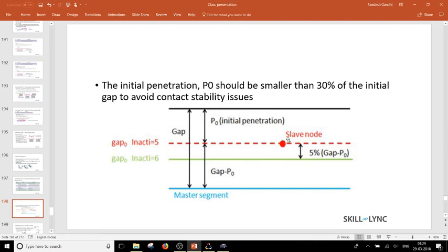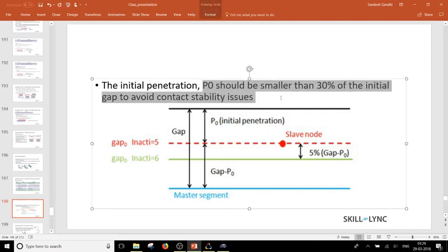And now what it will say for this particular node is, if it tries to move even inside this green line, then only I'll push it out. Otherwise, for this particular node, I'm fine with this particular region. Now this is a big adjustment as far as the rest of the contact goes, but to reduce the energy error, this happens to be the best practice for now. And that is why it is trying to suggest that to minimize that effect or that error